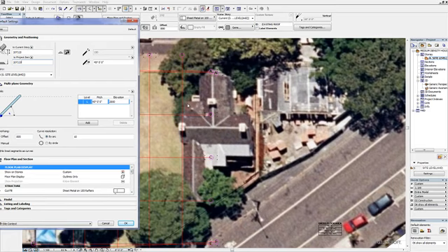It's also important to have the ridge levels of this adjacent building, because then we can also understand the bulk of the building itself, and also whether there is any shadow that's going to be cast on our building. Now, because we don't have a survey, we're going to leave the RL to project 0 of the roof line as it's defaulting, and then we'll attend to it when we come to look at the photos of the elevation of our building.